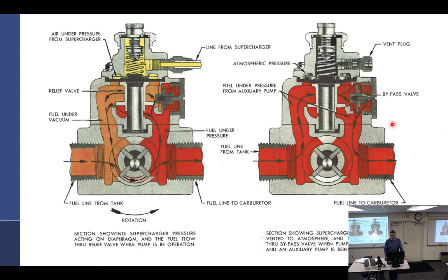All right, so we're going to start with this one over here. Engine is not running. Fuel comes through here. Does it go through the pump? No. Why not? Because it can't, because it's not running. So it's going to come up here and go through this, and there's a plunger-looking thing right here on a very weak spring. And so it pushes that aside and just finds its way right through without any problem whatsoever.